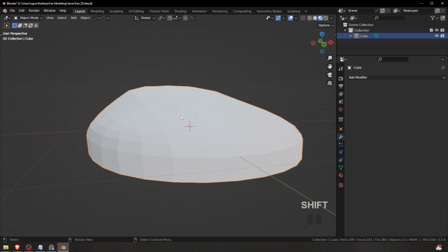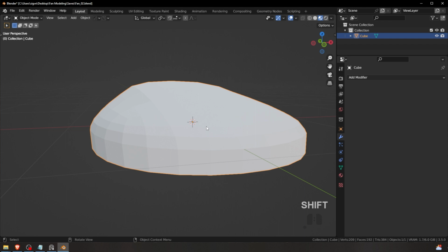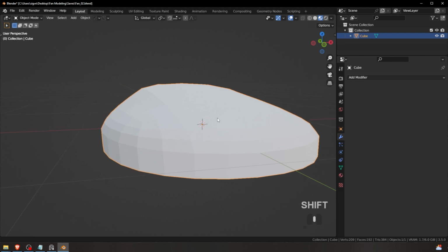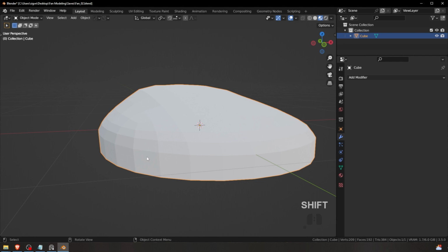So right now we need good shading, and if you're using booleans as well as subdivision surface, you usually need to go higher in polygon count at first, but later when you're optimizing, then you can optimize everything a lot, like with any regular different workflow.